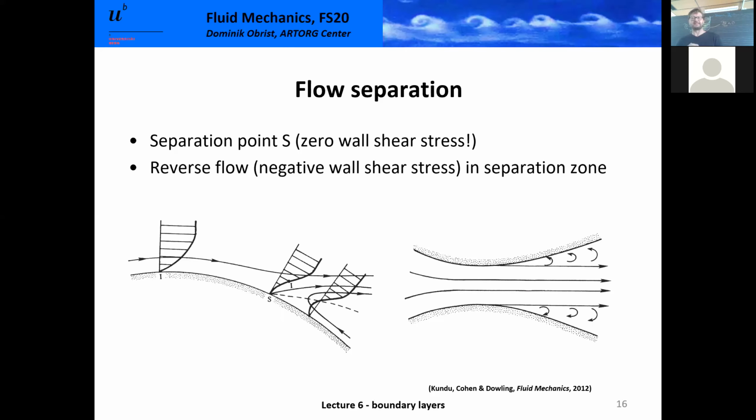It does not necessarily have anything to do with turbulence. So per se, flow separation does not have to be turbulent. Very often this gets confused. Flow separation creates stall. Turbulence does not create stall. Very often separated flows are turbulent, but in the first place, separation is the bad thing. Remember that, but we'll come back to it.